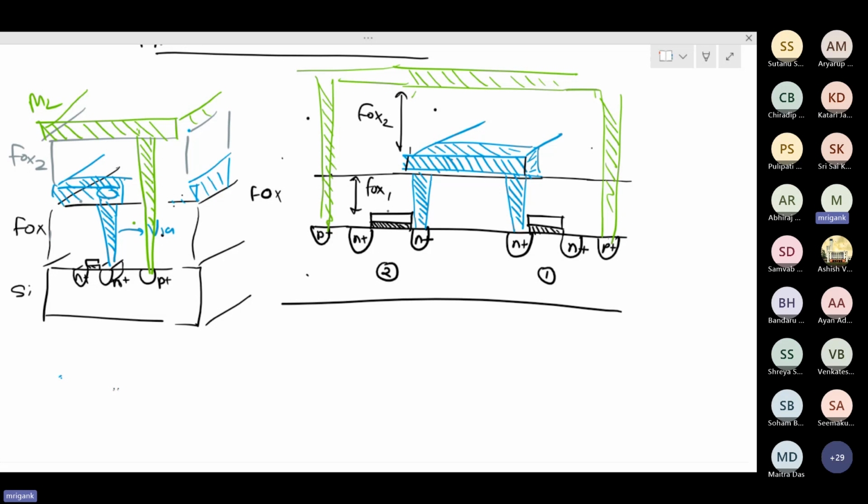So the main motivation behind giving you this overview of fabrication process was first to give you an idea of how the VT, the threshold voltage, will be dependent upon some of the fabrication parameters like the oxide thickness, work function, doping density, and so on. And second, the physical structure, actual connection between the MOSFETs in a chip, how will it be formed using this multiple layers of metal connectivities with the underlying silicon transistors. So this idea you should have.